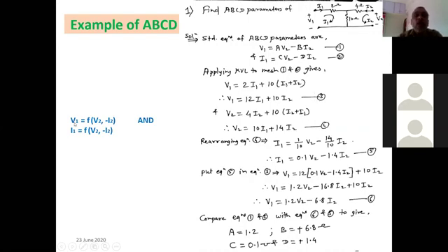What we want, the standard forms are, we should be able to express V1 and I1 in terms of V2 and minus I2. So if you observe I1 as a function of V2 and minus I2, and if you observe equation number 4, it has the terms V2, I1 and I2. We want V2, I1 and I2. So this equation you can form from the fourth equation. Only you have to rearrange the terms. That means you have to write I1 as a function of I2 and V2.